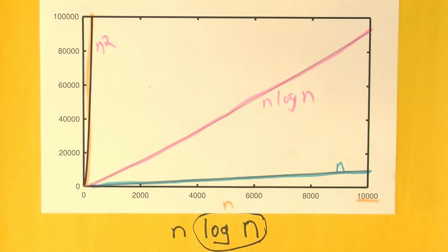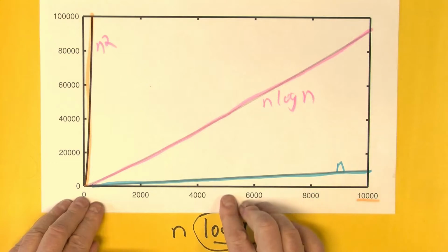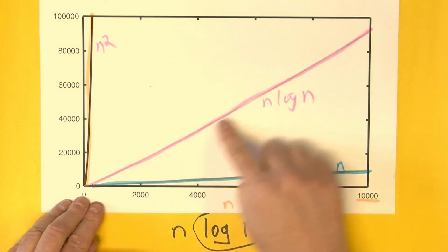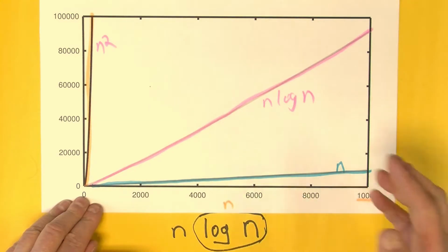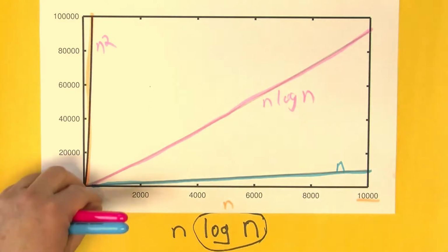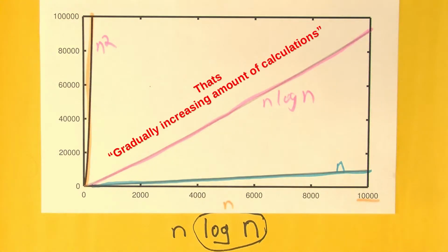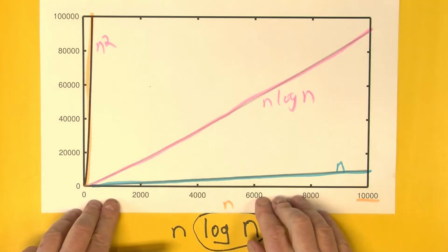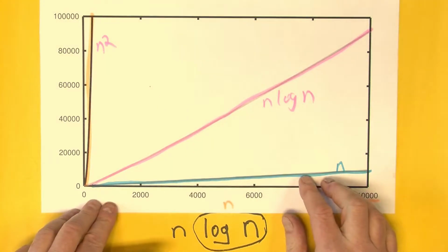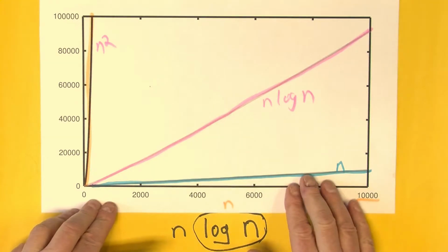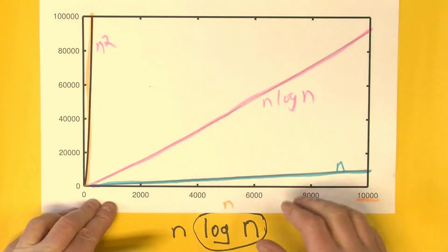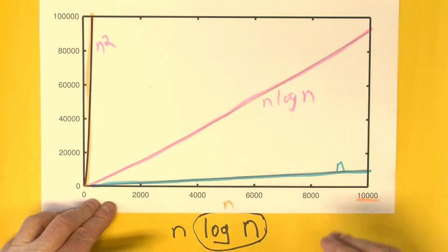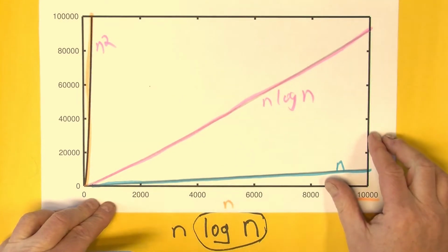So for virtually all applications, the fast Fourier transform is in fact the way to go, because you can do larger and larger data sets with only gradually increasing amounts of data. There are a few exceptions, and that is if you only had a few points on your whole data set that actually had a value and were zero elsewhere, then you might find that some sort of a brute force method is better, and I know that's done with astronomical signal processing.